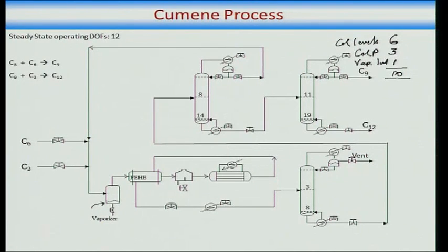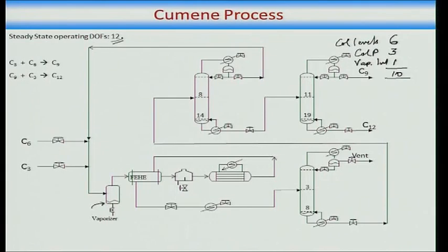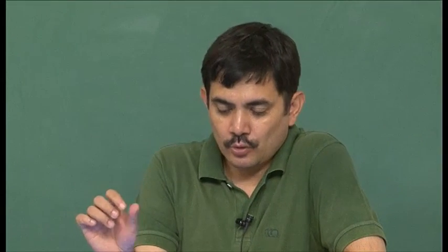Alrighty. If 10 valves go, what I am left with is 12 things that can affect my steady state. This is the steady state operating degrees of freedom. And now I say okay, I will optimize these 12 degrees of freedom for a given throughput. So, if it is a given throughput, I am left with 11 out of 12, 1 is setting the throughput. Now 11 degrees of freedom remain. I optimize these 11 decision variables to, for example, maximize my plant operating revenue. Okay.